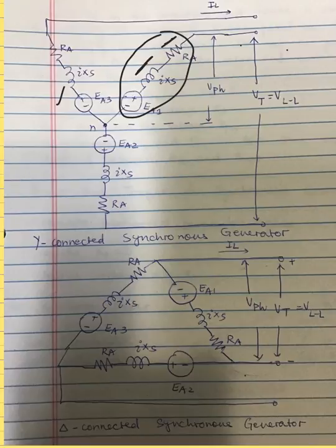So with respect to the equivalent circuit, what we do for synchronous generators for the armature side or for the stator winding is use a per phase equivalent circuit to do the analysis, and then we say the same thing applies to the other phases. So in the per phase equivalent circuit, we only use one phase, one line, and the other as the return path, and it could be true for a delta or for a Y, because that does not matter in the case of per phase. It's only a single phase quantity.